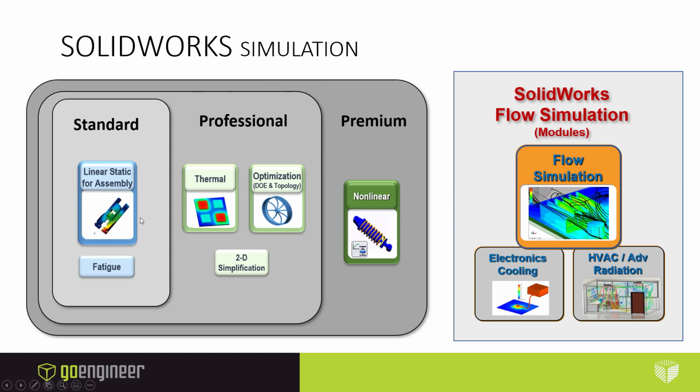We saw a lot of this guy here, Simulation Standard, static analysis. We ran all those stress studies that we ran. They all used this tool here. So if you're going to do thermal stress studies, this is likely going to be one of your main tools. Now it just depends on where you want to bring those temperatures in from.